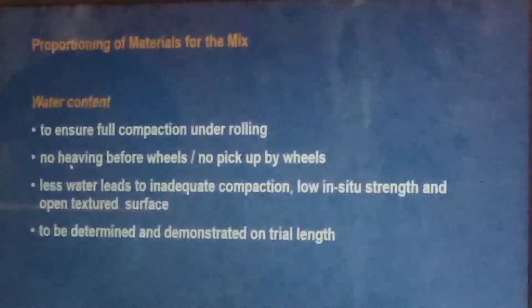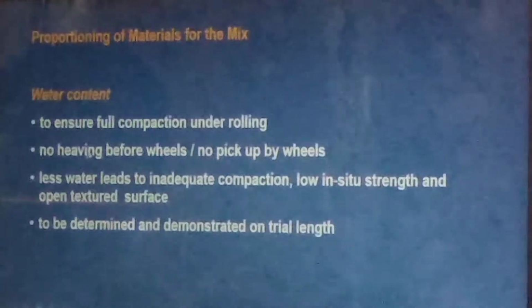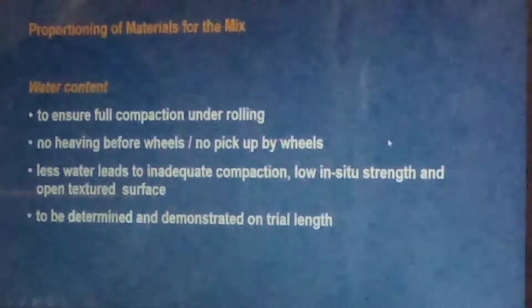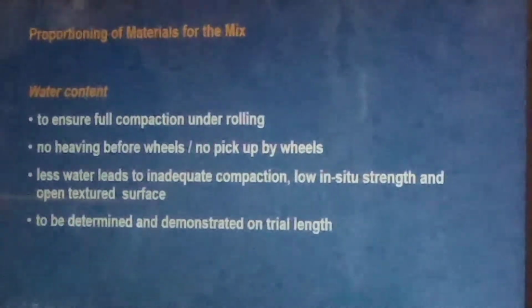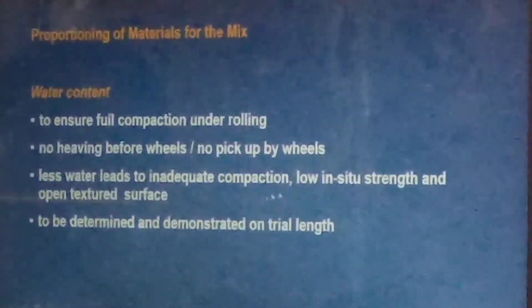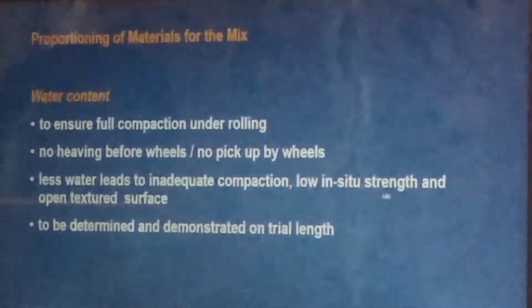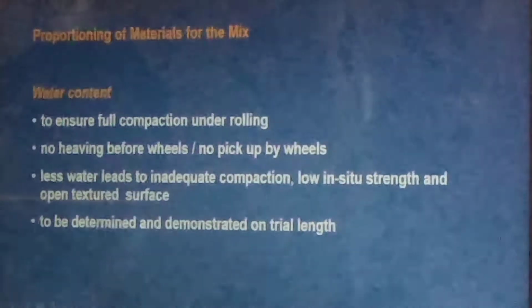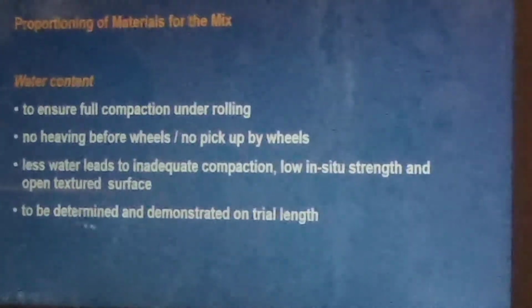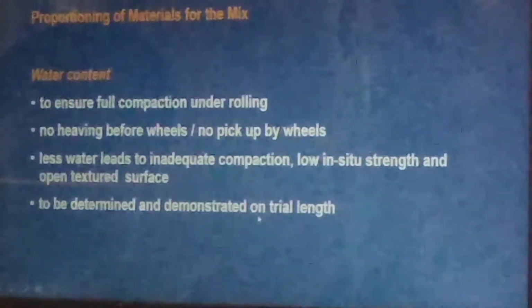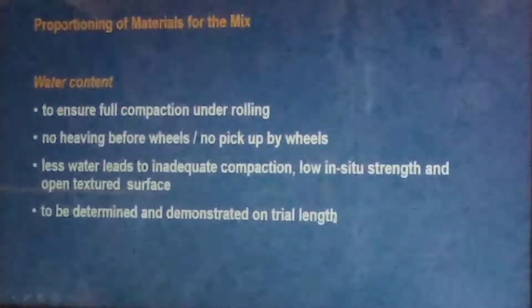These things are not to be observed. Heaving not to be observed during rolling operation. Please remember, less water always leads to inadequate compaction, low in situ strength, and also it gives open textured surface. The water content always to be determined and demonstrated on trial length or what is called mock-up.